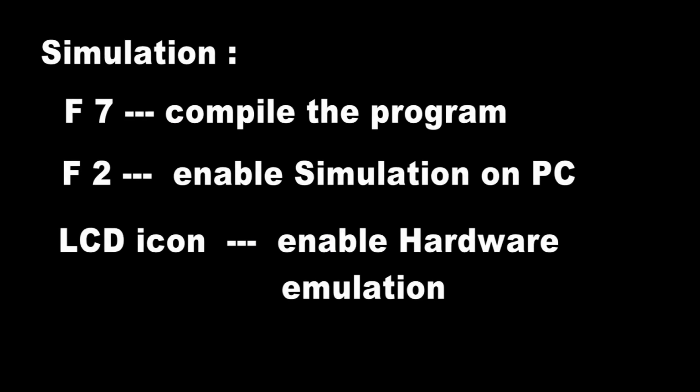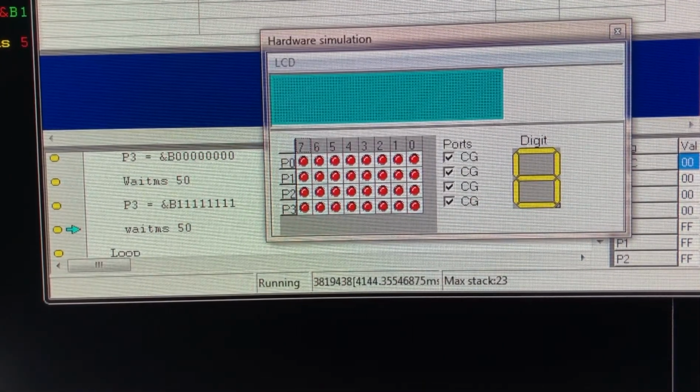Let's continue by simulating the program, and here you go. You will see that all the ports of P3, or the 8-bit ports of P3, are being commanded by one instruction to go logic 1 and logic 0 at the same time alternately.